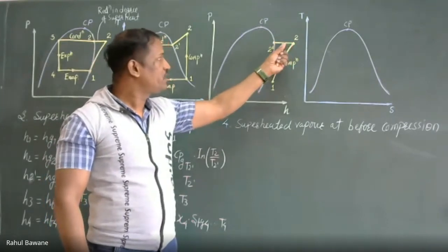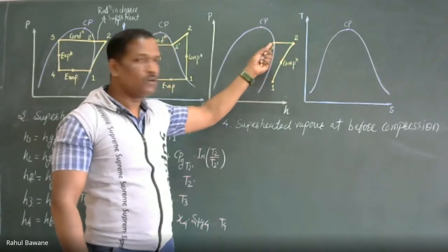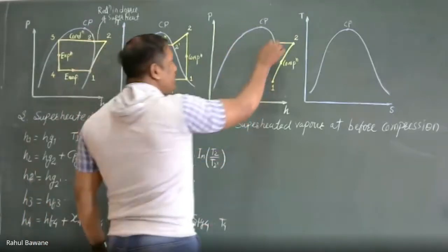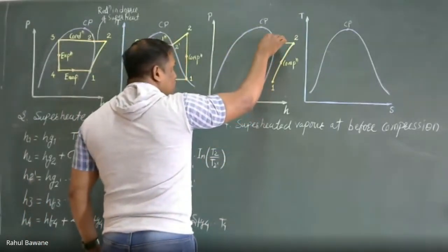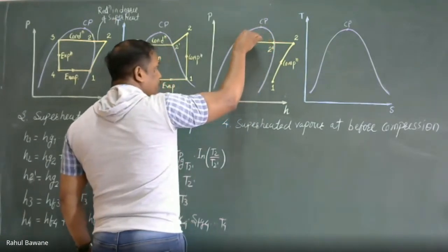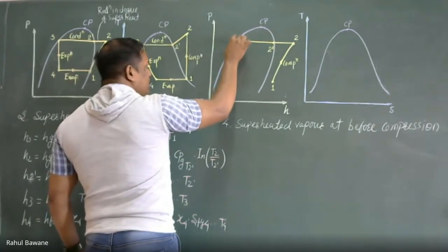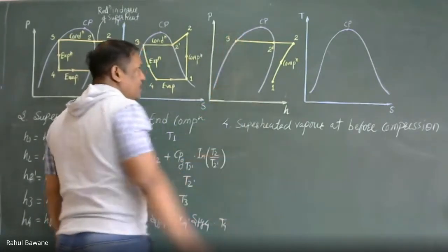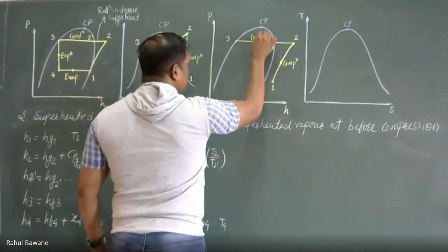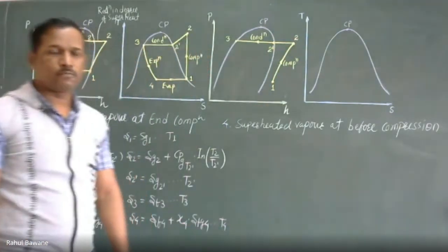So temperature is reducing and we are bringing vapors from superheated condition to dry saturated condition. Then we are removing latent heat, so its phase changes. First it becomes wet vapor and last it becomes saturated liquid at 0.3. So this is condensation. This is the portion where we reduce the degree of superheat.